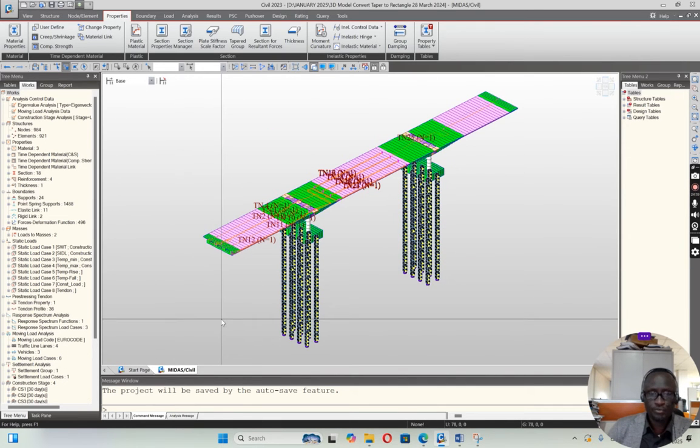So the issue of profiling, the issue of identifying and laying out the tendons: you must first understand how to determine the neutral axis of the member section. You also need to know the different patterns of laying the tendons, both transversely and longitudinally in the bridge direction.